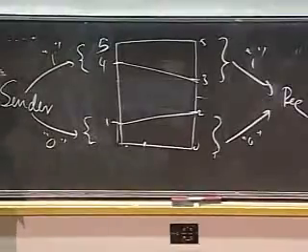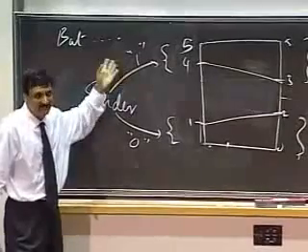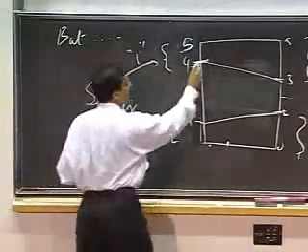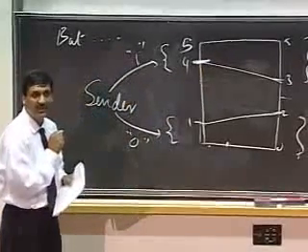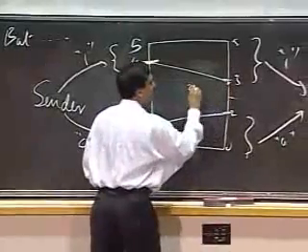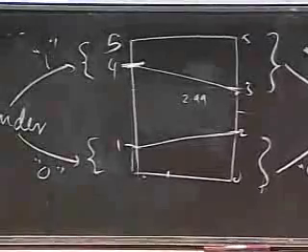Can someone tell me what's the noise margin here for a 1? 1 volt. And the reason is that the lowest voltage a sender can send is 4 volts. If the 4 leaks down to 2.99, that's in the forbidden region. I'm in trouble.